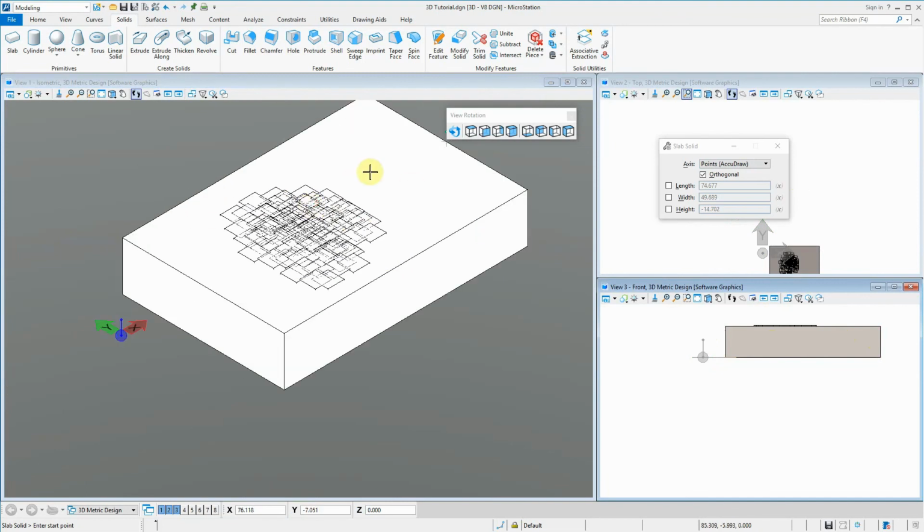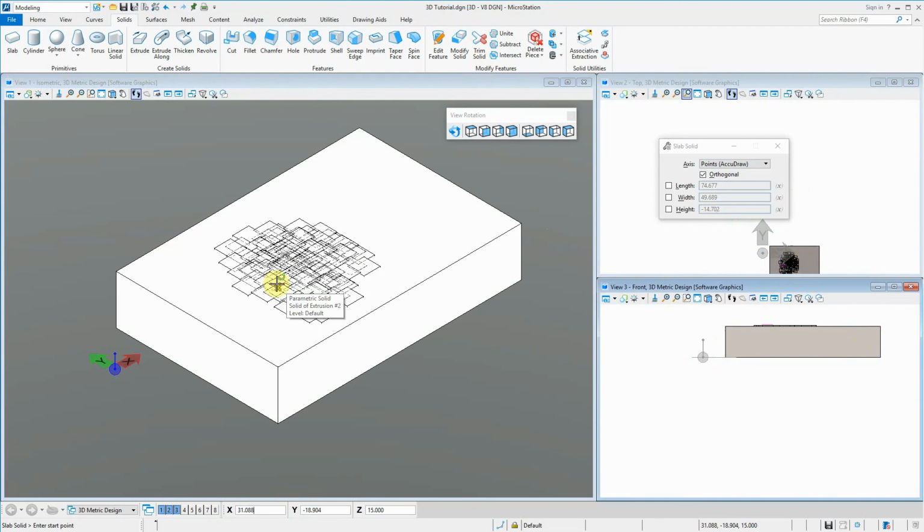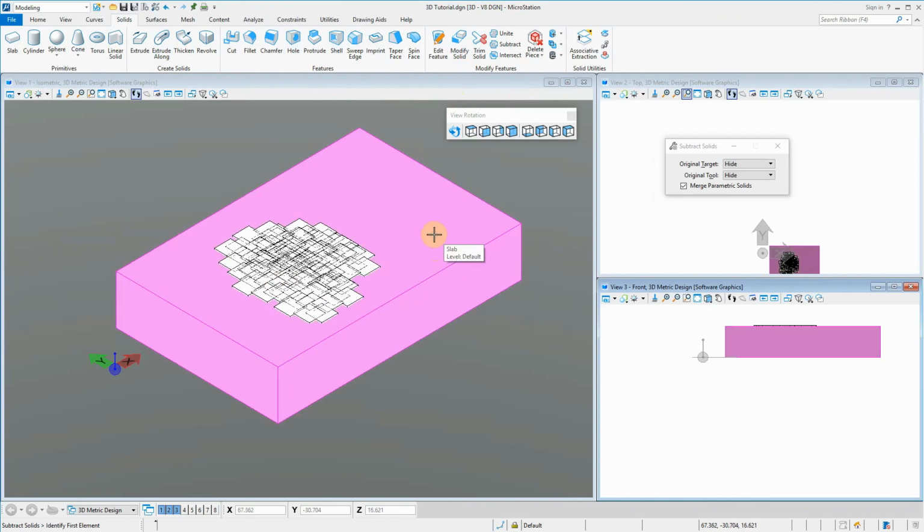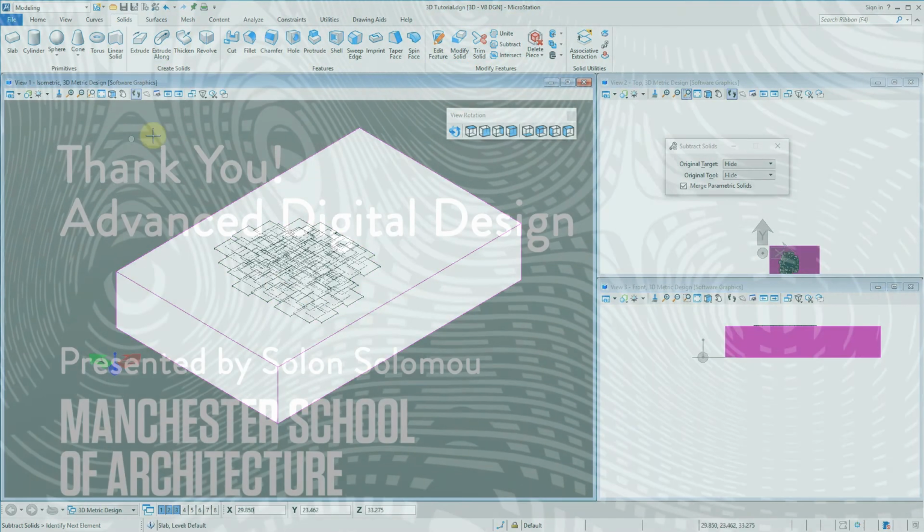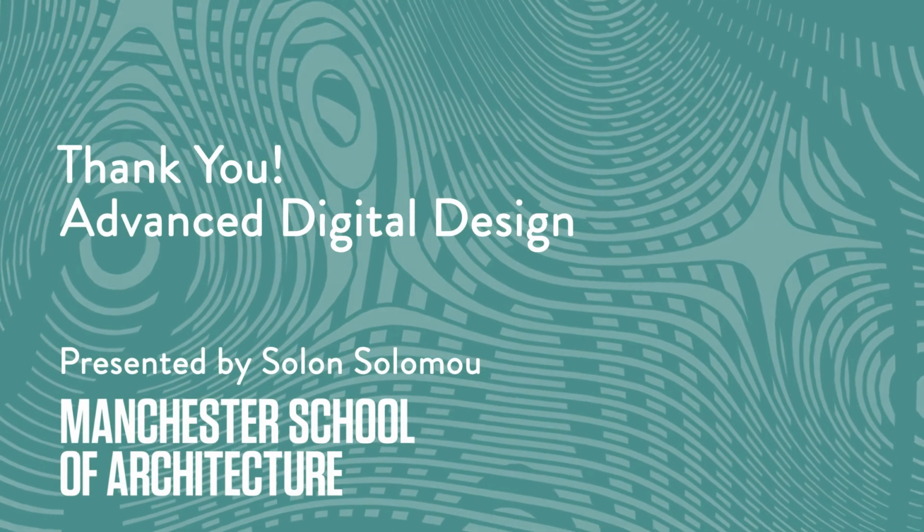So what I'm going to do now, I'm going to create a Boolean operation. This is what this software is very good for, if you have very complex geometries, and you can import geometries as well from other software. It doesn't necessarily have to be created here. But what you can do is a Boolean operation, whereby you can press space, go to the modify tab, and there are the Boolean operations. And we do a difference feature. So we first select the thing we want to delete from, and then all the other elements that are going to be deleted from it.